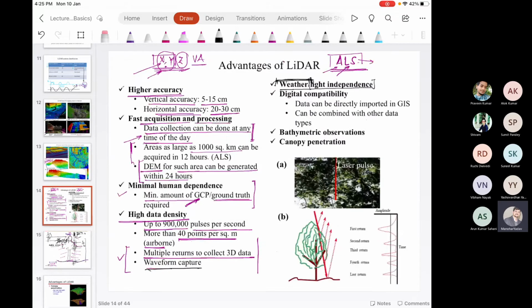Okay. So though in general weather we can do the remote sensing, in the heavy rainy season, if there is heavy rain outside and significant water on the target points or surfaces, we avoid going with laser scanning.